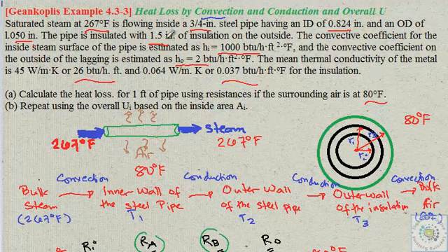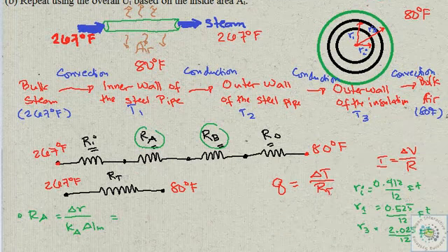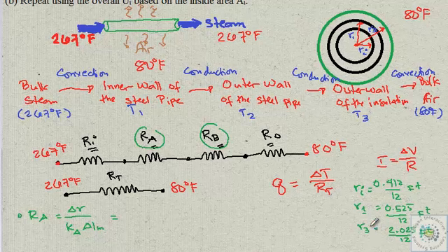So we manipulate that, and I hope you'll be able to get this by yourself: how do you find the outer radius of this whole setup, the outer radius of your insulation? Now, delta R will simply be the thickness, R2 minus Ri, and values are already given for steel. We are given some values of K.